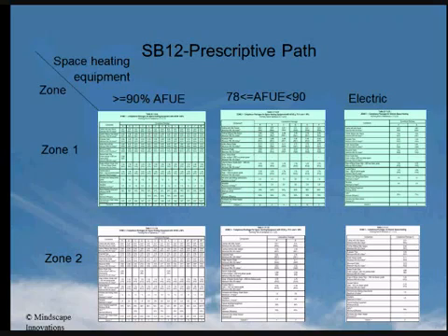The number of heating degree days can be found in the Ontario Building Code Supplementary Building Standard SB 1. Zone 2 includes all municipalities with 5,000 heating degree days or more. The tables are also arranged according to the type of space heating system planned for the home.